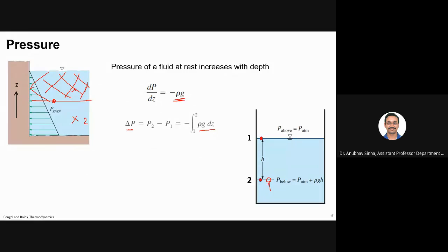So there will be some normal force that is supporting it from the bottom, and from the top it has to sustain the weight of all the fluid mass that is on top of this, all this height h. If you talk about this column only, whatever fluid mass is above that particle, that mass is supported by this particle, right? This column of fluid will have mass rho, density, into g into whatever height is there, per unit area.